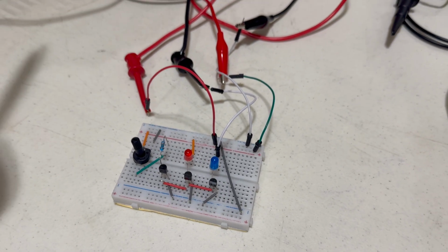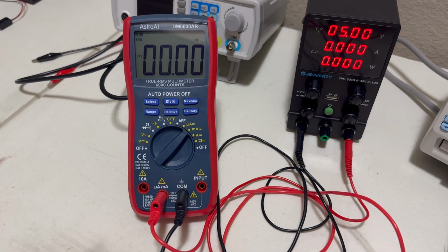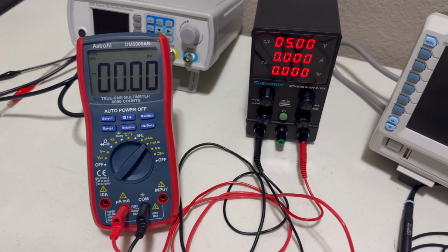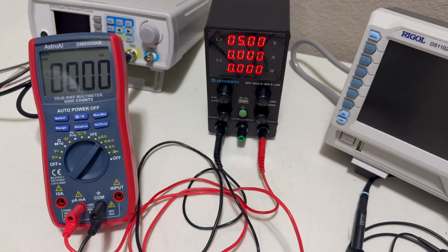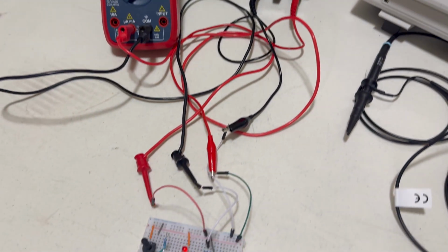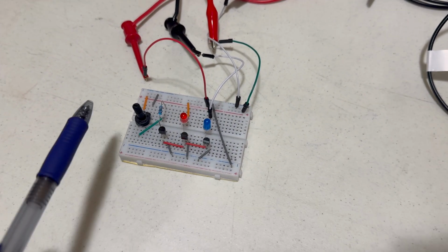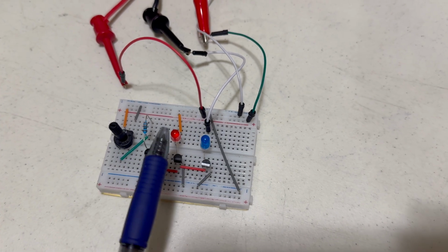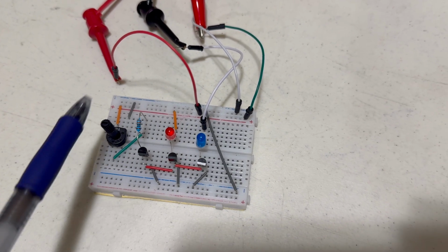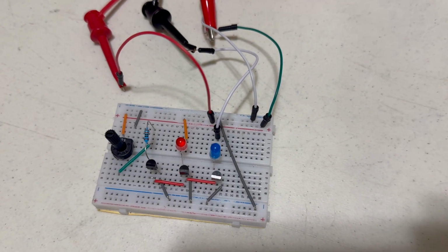We're also having our meter here to measure the current on that single branch. That's part of that third branch. So we're also using a 5 volt supply here to power the whole thing. And so we don't need protection resistors for these 2 LEDs because the current of each branch is mirrored from the resistance on the first branch. So there's no need for a resistor on these 2 LEDs.